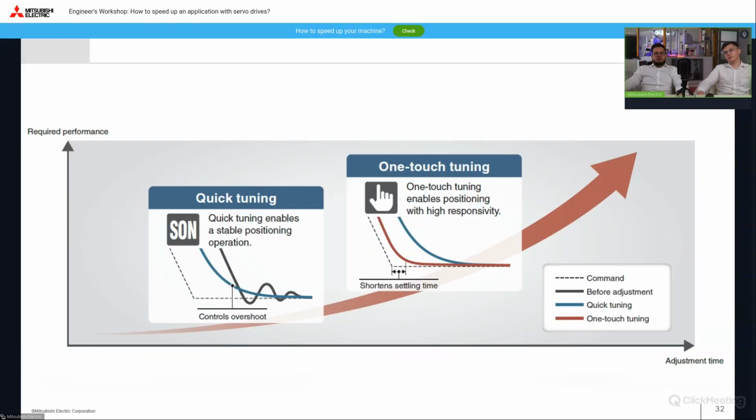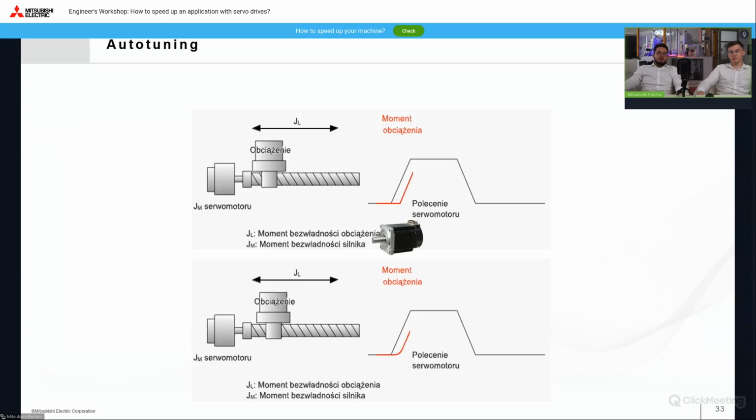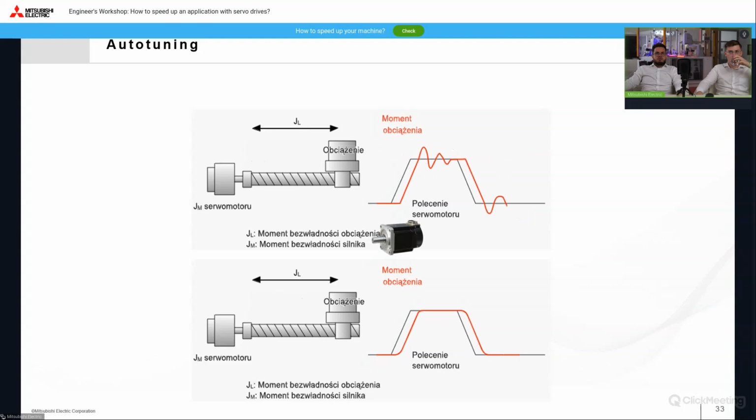Another important topic affecting productivity will be the control algorithms inside of the servo drive, resulting in the effectiveness of auto-tuning. In the animation, you can see the difference between a well-functioning regulator and one that is not performing well. A very efficient regulator loop and auto-tuning algorithms can significantly improve the cycle times as the servo will arrive at the exact point without any overshoot or even oscillation in the end position.